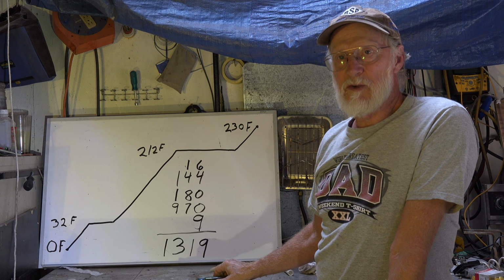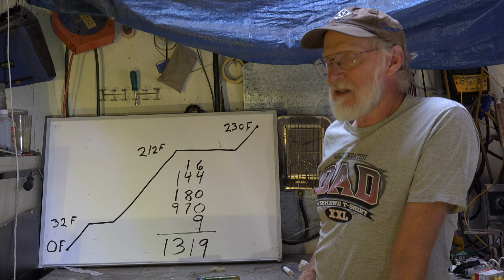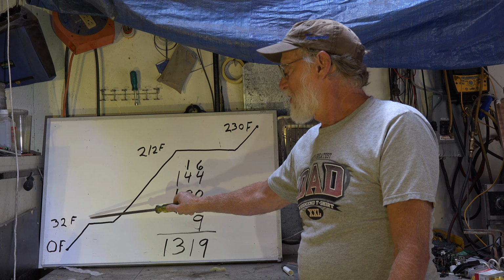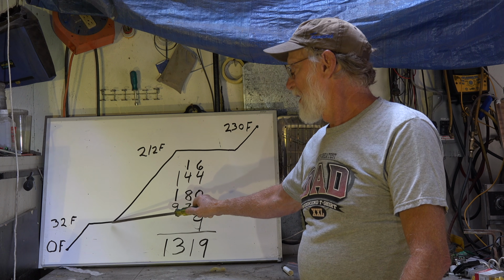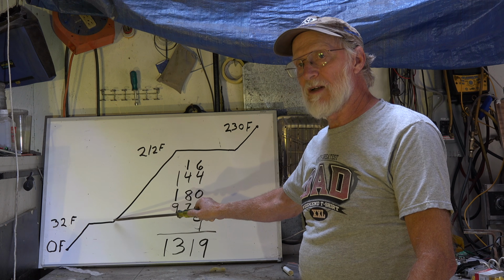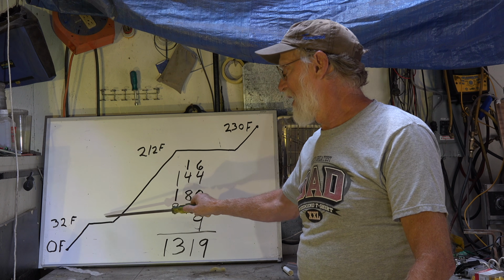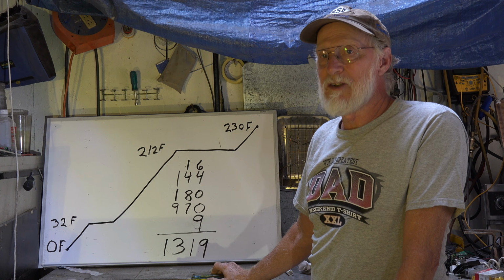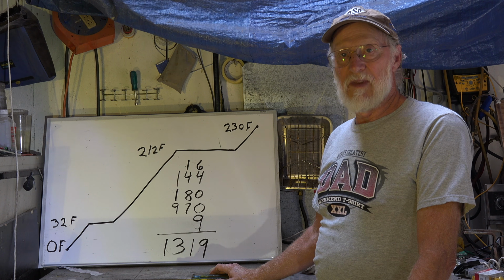So I'd have to have a refrigeration system that did 10 degrees. But if that substance was liquid water, I would also have to take that 144 BTUs out of it to get it to cool. Anyway, that's it on this one.